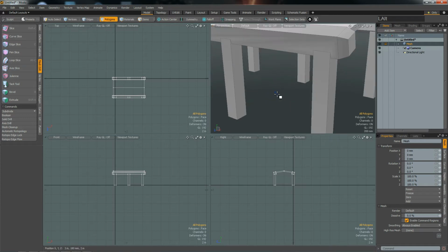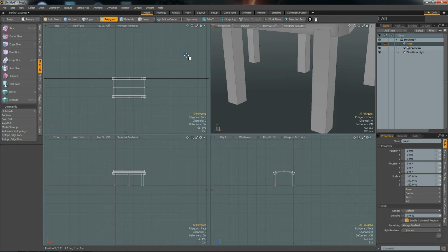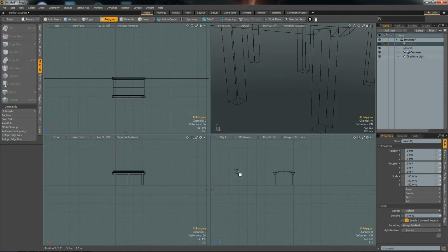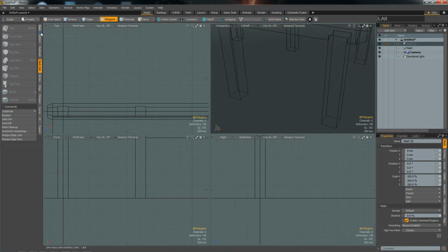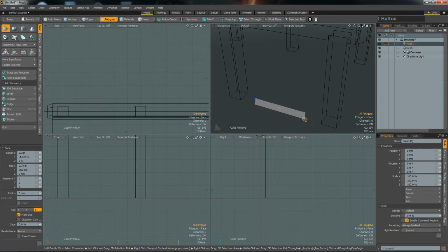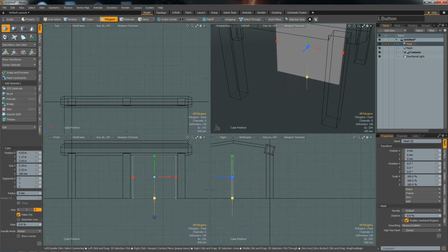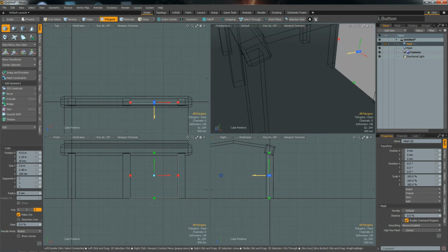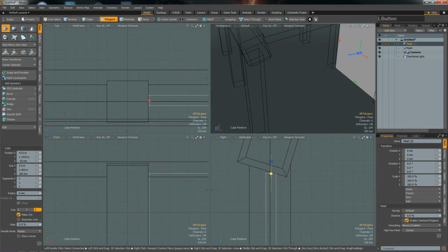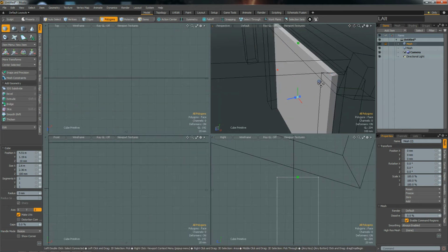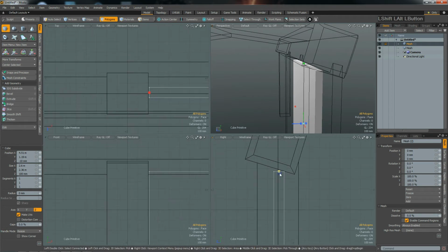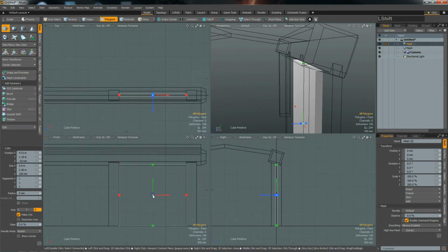Now there are again several ways we could do this. I could, for example, create a new mesh layer. Now go in here and drag out a shape like this and try to scale it until it really hits in there. But even if I did that, we would still have some issue on the roof because it's slanted, and I would have to start fiddling with vertices, aligning them perfectly up there. That's one way, the hard way.